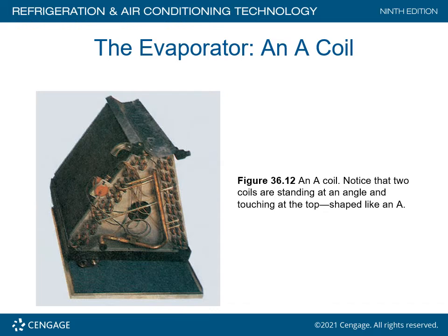And the other thing is, and you can't really see it here, but this coil has the appearance of being very, very dirty. One of the things that I pay very strict attention to is evaporator coils that get full of dirt. And the reason why they get full of dirt is if you look below, they have a cheap filter on this illustration. The cheap filter is basically no filter at all. Basically lets 90% of the dirt go through. That dirt's going to end up underneath this evaporator coil.